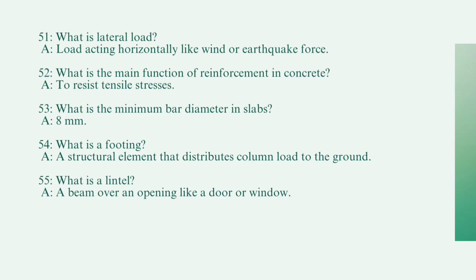Now question number 51. What is the lateral load? And the answer is load acting horizontally like wind or earthquake force. Question number 52. What is the main function of reinforcement in concrete? To resist tensile stresses. What is the minimum bar diameter in slab? It is 8 mm. Now the next question is, what is a footing?